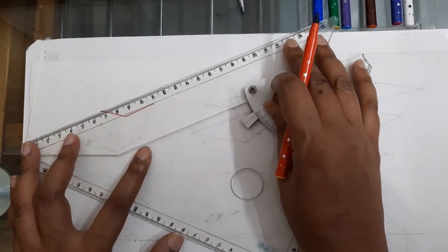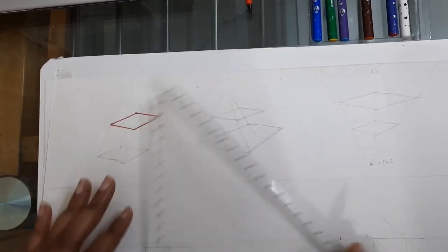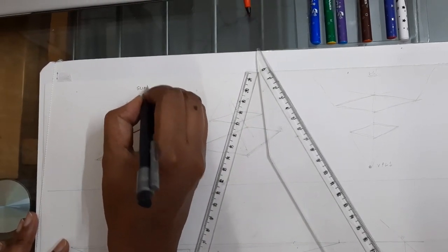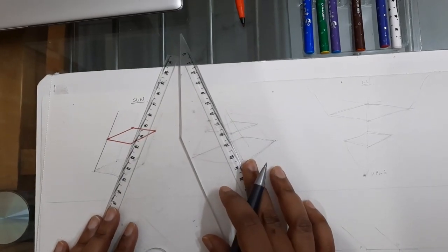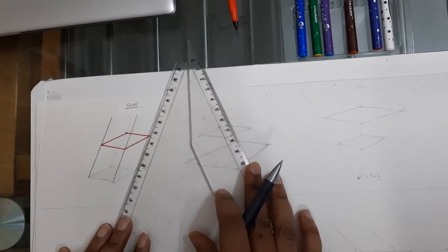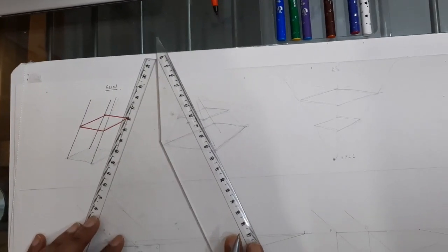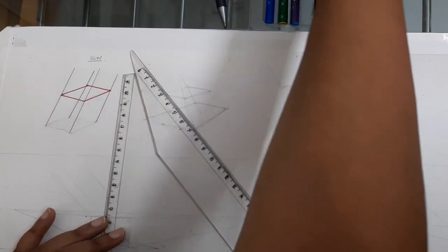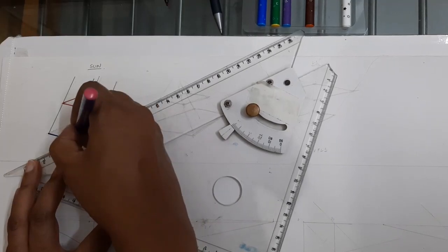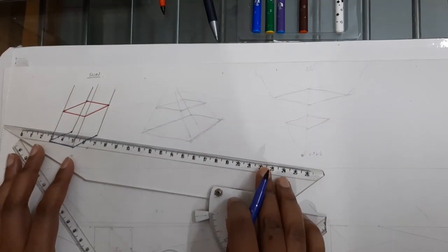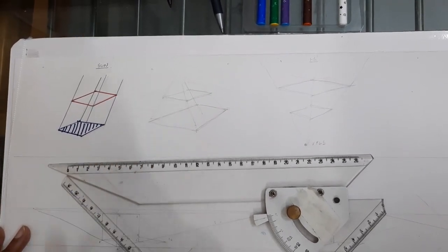This is the first method, in which this is the object we are making. In this method we are assuming that the light rays are coming from the sun and are parallel to each other. So these are the light rays that are coming from the sun and passing through the corners of the object. This I am doing to make the sciography on the ground. So you can see this is how the sciography has been drawn on the ground by the rays that are parallel and coming from the sun. So this is how a sciography has been constructed from the rays that are parallel.